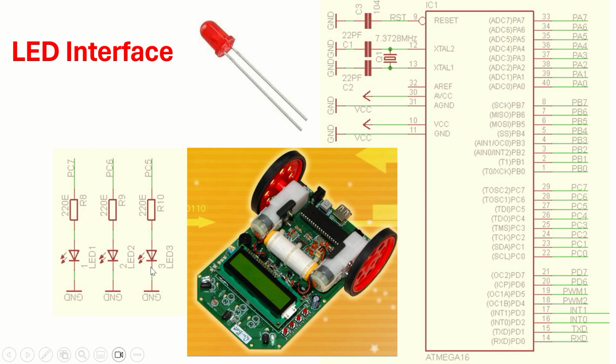So what do you mean by good enough? For this light emitting diode to be forward biased, you are supposed to apply at least above 1.2 volts to the anode, the positive side, because the LED itself will take 1.2 volts as a drop. So above 1.2, it could be 3.3 volts, 5 volts, 50 volts, 100 volts, 1000 volts. Anything above 1.2 volts, the LED will be on, forward biased.